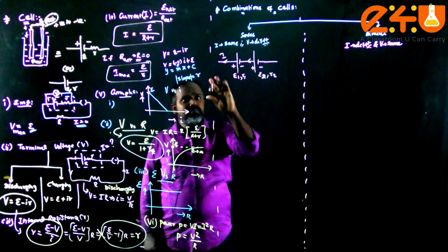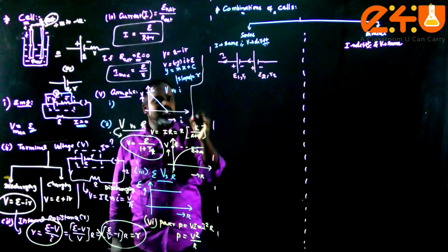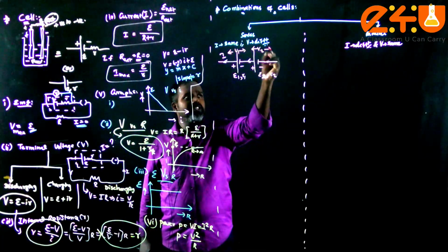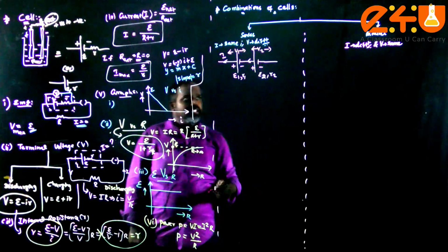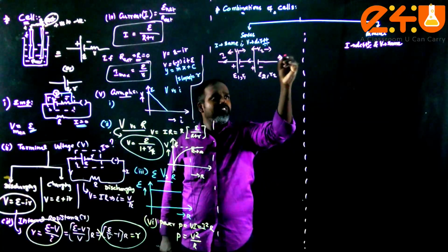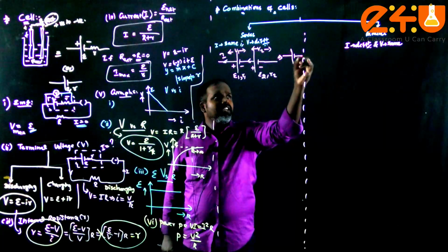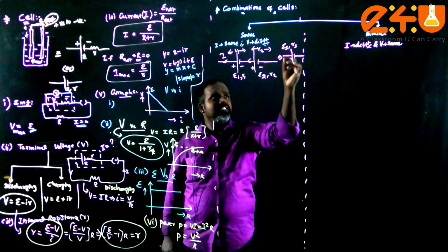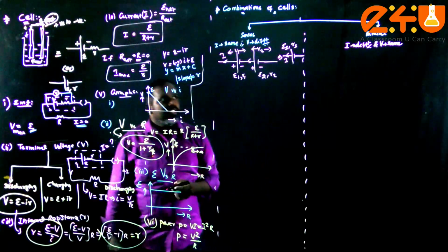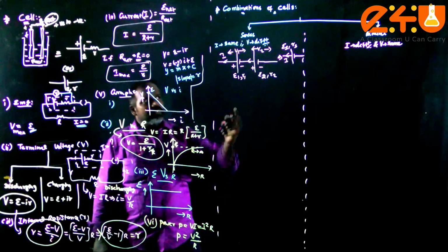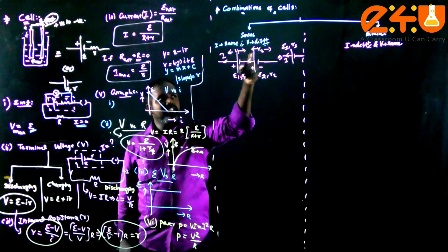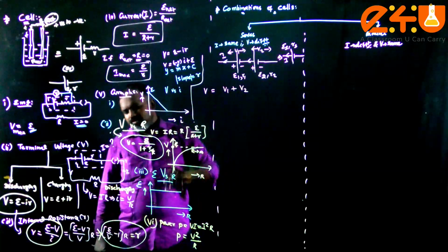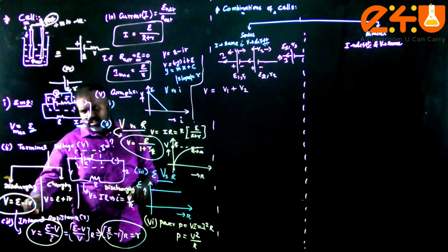As we said in the resistance part, here also the terminal voltages are different. So this is V1, V2. The equivalent cell is the cell which will deliver the same current, with equivalent EMF E series and equivalent resistance. That is called the equivalent cell. The same expression we are going to discuss. Since V is different here, the total voltage is nothing but V1 plus V2. We know the expression for V for a discharging circuit, E minus IR.